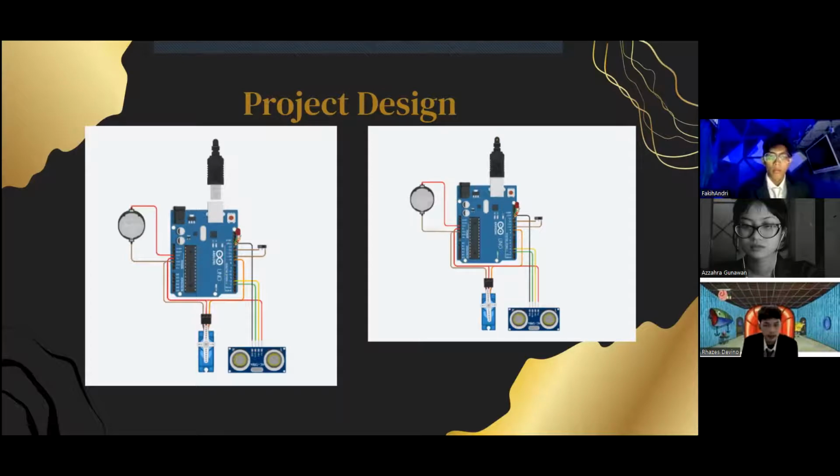And there is a servo, a blue servo, so that the servo can be used. We connect the ground to ground, power to 5 volts, and the signal to digital 9. And after that, the servo is ready to use.